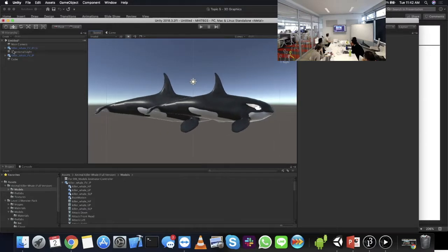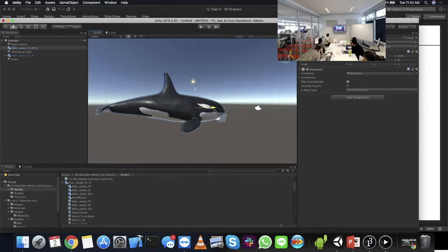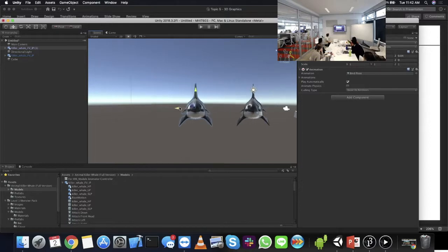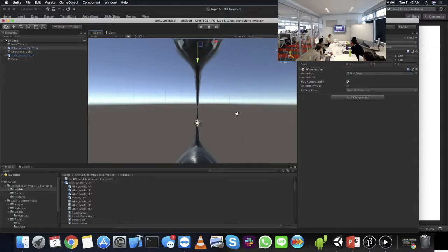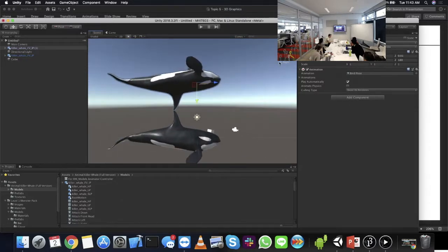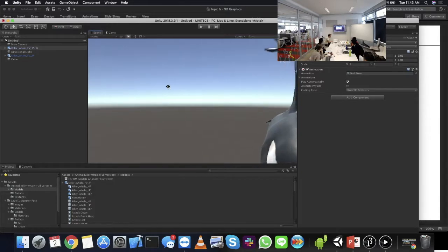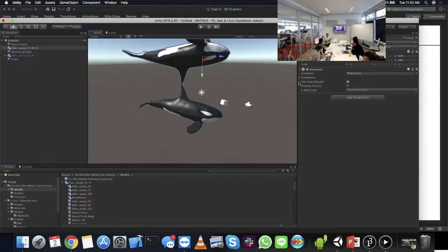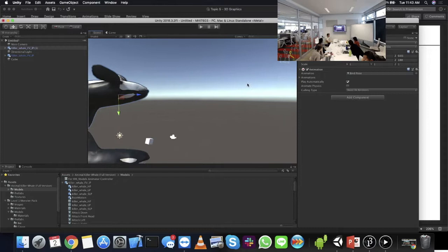So what I can do now is, because we've lost this sense of depth, it actually makes it a lot easier to align things. So I can align it in that view and I know that it's going to be aligned, and I can align it in that view and know that it's going to be aligned, and then I can align it in that view. And if that is aligned in isometric or orthographic view correctly, I know that if I go back to perspective by clicking on it again, that will be perfectly aligned, because we've effectively aligned it in a view that gives us accurate dimensions rather than trying to do it in something that looks realistic.